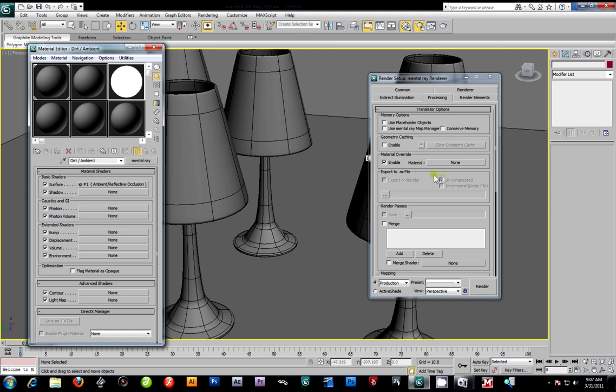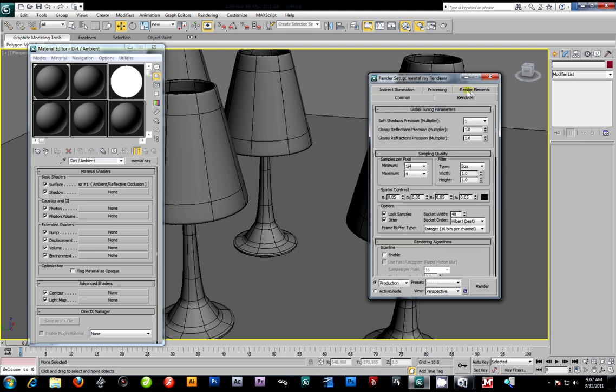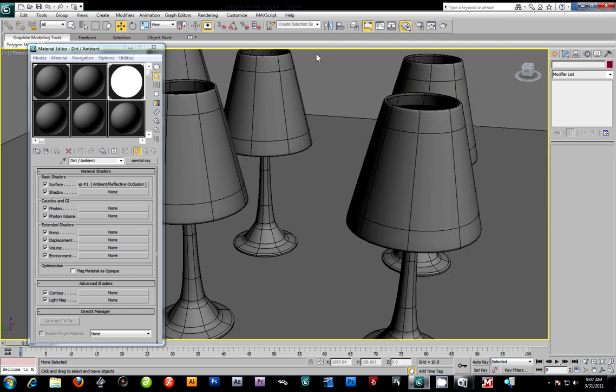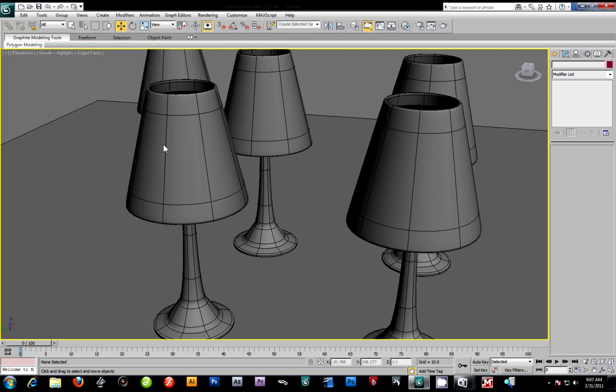I'm going to go back to my renderer tab right here now, and we're going to change this to 1 and 64 and to Mitchell. Like I said, I learned this technique from Everflow, with a slight few adjustments, but from everflow.com, and I explained about them a little bit more in past tutorials.